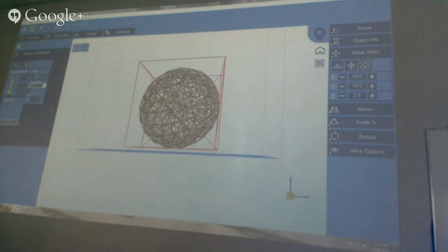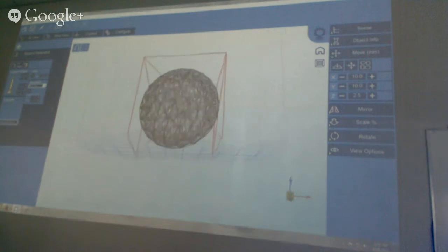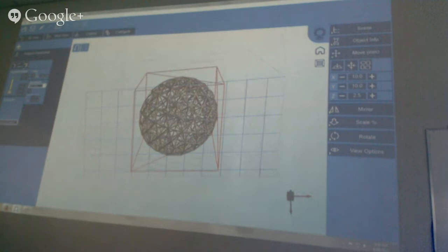And so to manually add supports, first we have to assign a shape for your support. The shape looks like this. There's a tip size, and then gradually going up, the bottom is the largest. It's like building a bridge, you need pillars. So usually for this one, we would do like 0.3, 0.5, 0.7, 0.9.